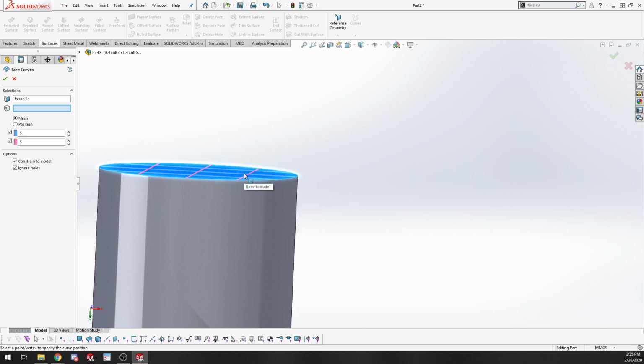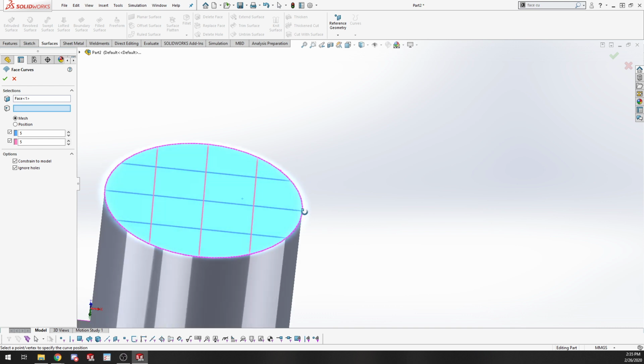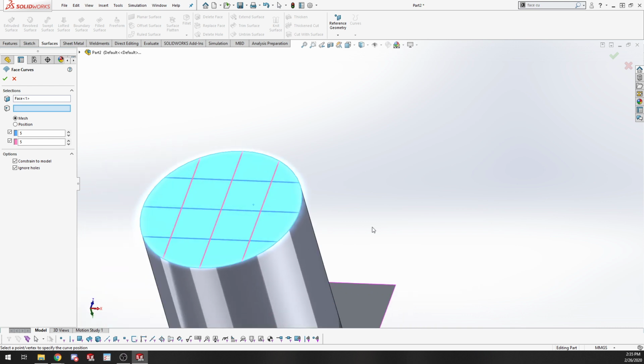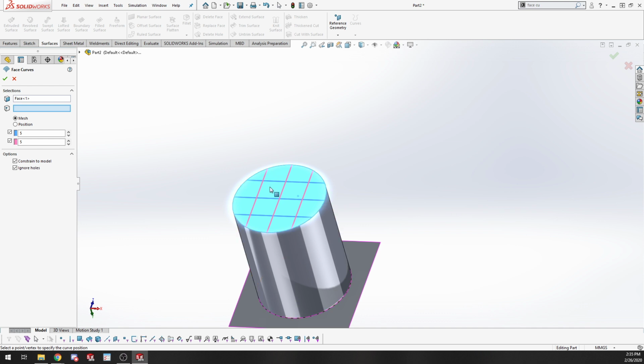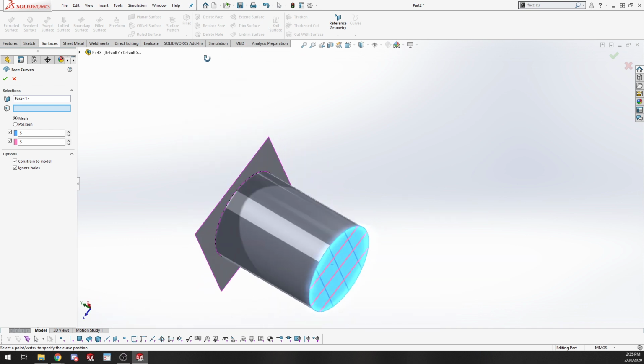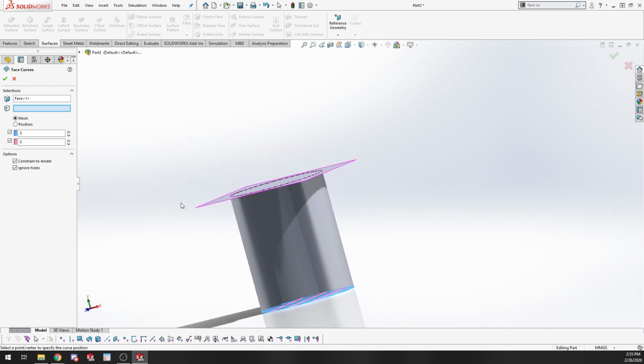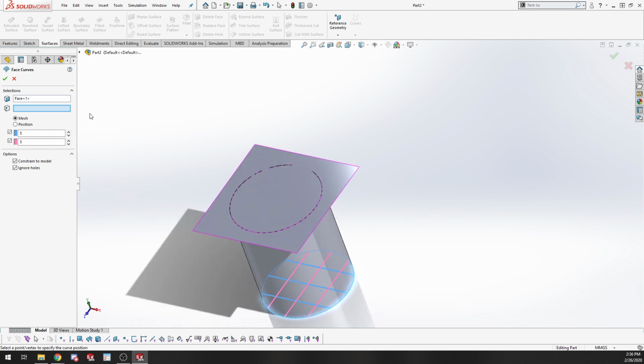If all these lines come to a point in the middle, it's going to try and evaluate a spline between 2 points that are right on top of each other. It's going to start to create these really close to each other, and the spline is going to just shoot up this random bit that goes to the sky or wherever else. So that's something to keep in mind. Kind of cool what SolidWorks is doing behind the scenes, but also something to watch out for when you're making your parts. Do this analysis sometimes.